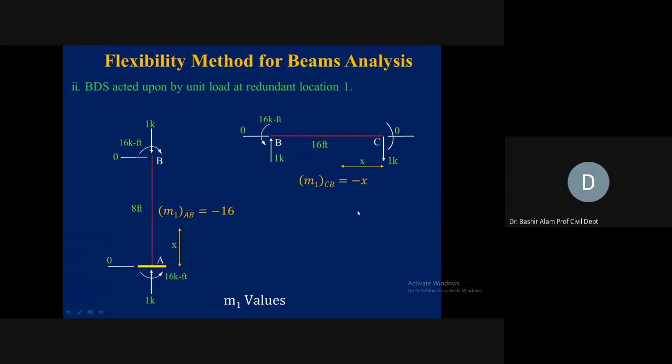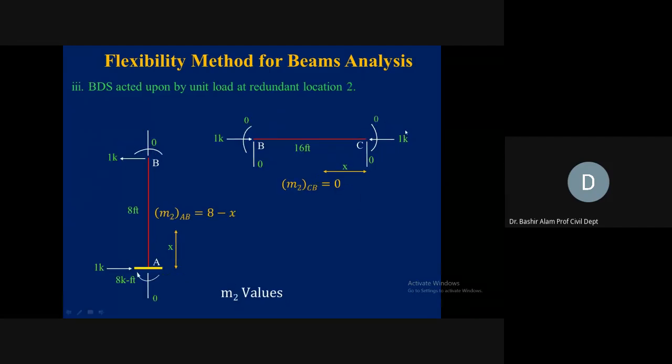Next, now, as 2 degrees indeterminate, corresponding to AR2 we need to apply it leftward directed, as AR2 was, so 1 kip we are applying in the same direction. Analyzing member BC: leftward, so here we have rightward, summation of Fx is satisfied. Upward and upward 0, because we don't have any action in the vertical direction.